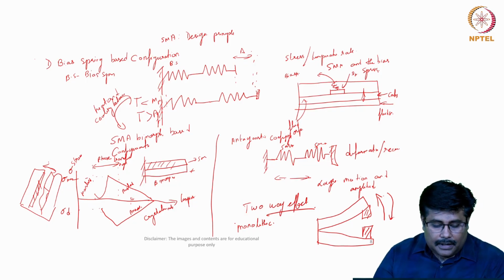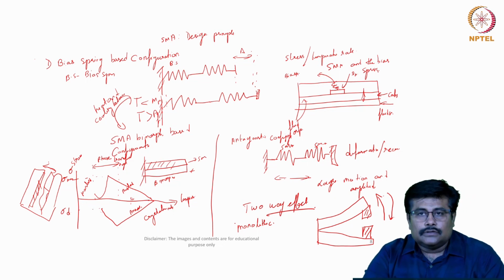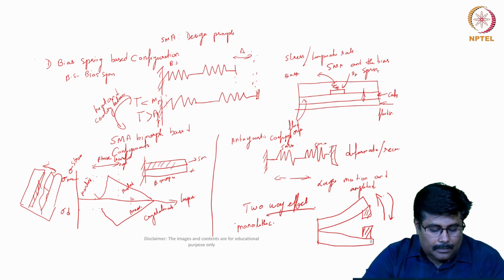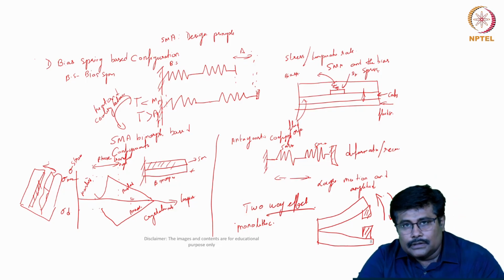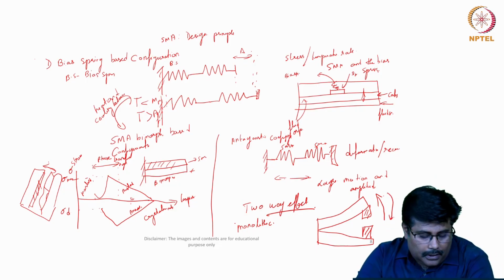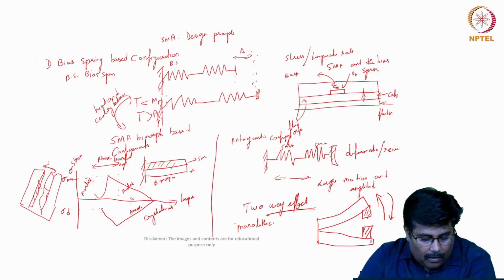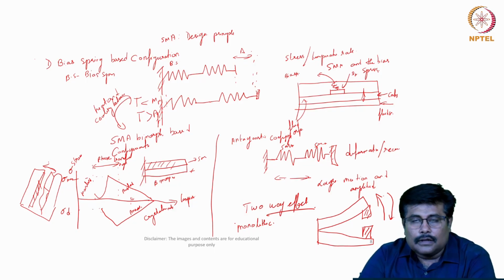The crystallographic transformation can only occur if the material is crystallized. The crystallization of the material is achieved by heating the material at high temperature, typically in the range of 500 to 800 degrees Celsius after the forming process. If the annealing step is not conducted, the proper crystallization will not be present, and consequently the material will not exhibit shape memory property, but it will behave like a conventional metallic material.